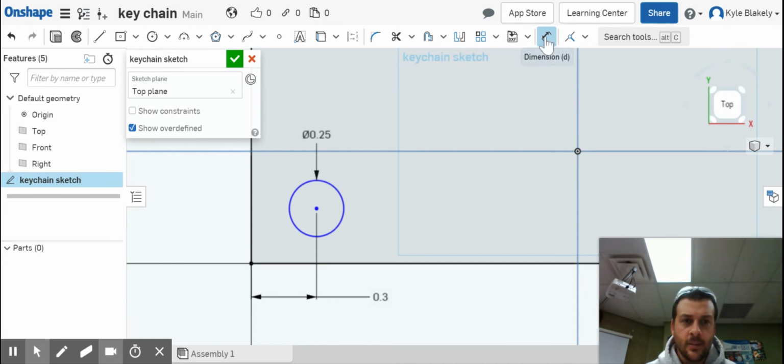and then hit enter, and then say I want this circle to be the same distance from this side. I can click on the dimension tool again, click on the center point, click on the side, drag it over, and it can work. Try one more time. If you hit the escape key, that usually lets you start over. There, center point, there, click once, 0.3, enter.